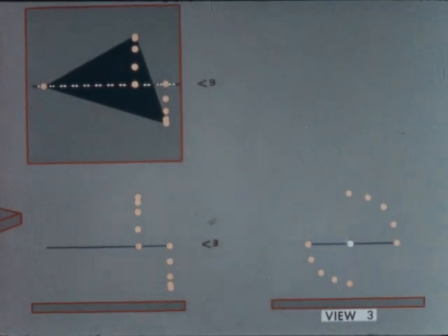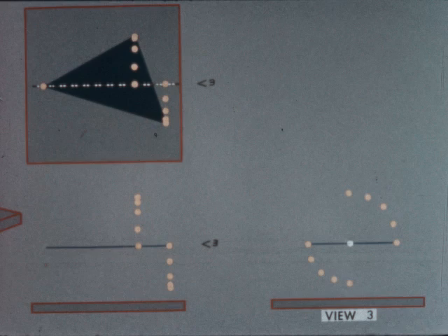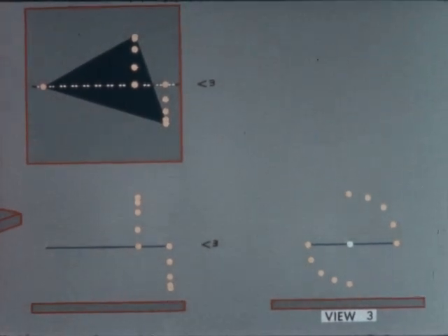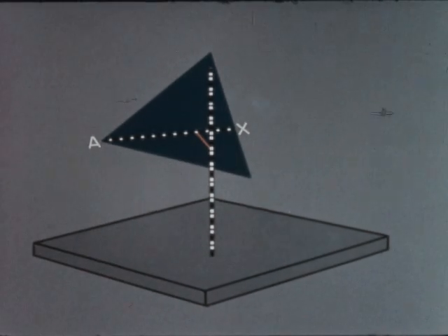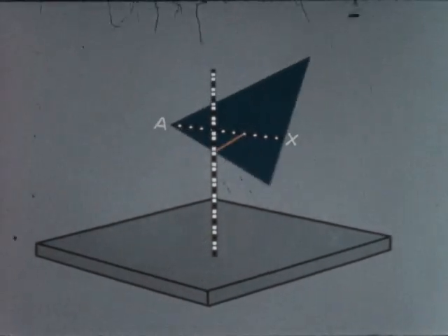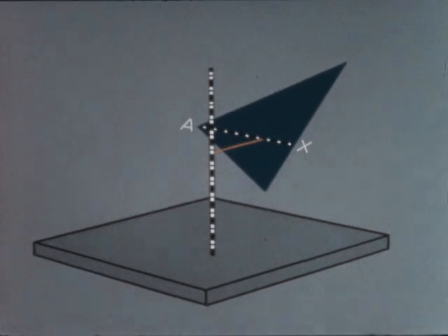A plane revolves about a line on its surface as an axis. Each point of the plane follows the path of a circle. When the axis of revolution is outside the plane, a suitable line is chosen on the plane, and this line is revolved to its new position. The plane is then reconstructed on the chosen line.